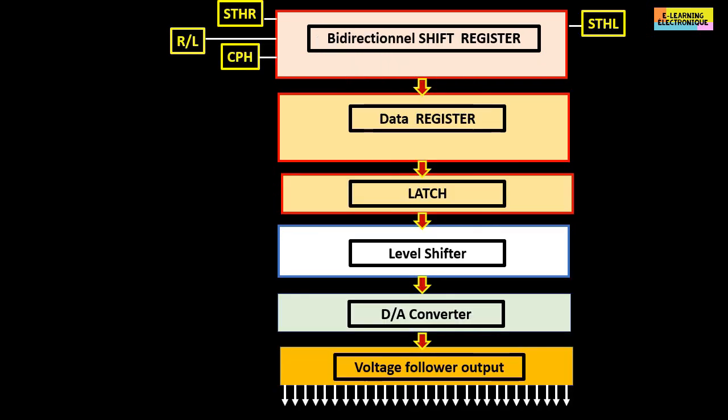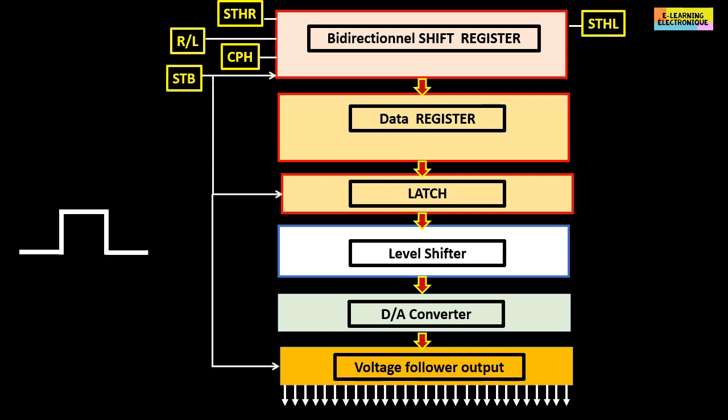In the datasheets of the source drivers, additional circuits such as a level shifter can be found, but the general principle of operation remains unchanged. Here STB is used as a clock signal acting on several levels with various functions. On the rising edge of this clock, STB has a reset function on the shift register and at the same time a data transfer function from the data register to the latch. On the falling edge of STB, the analog voltage generated by the DAC is transmitted to the buffer.